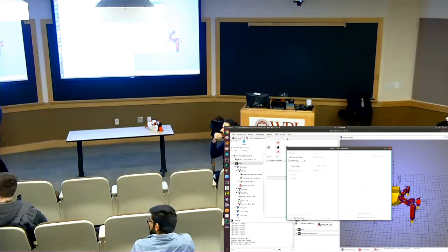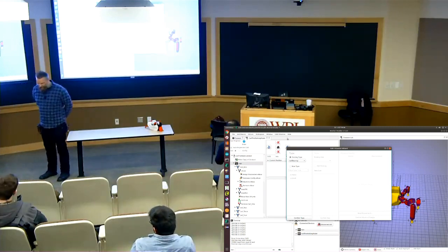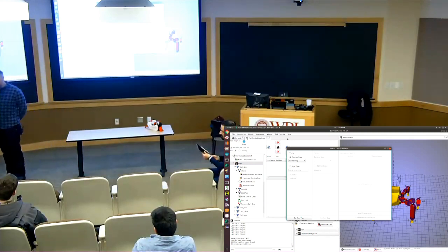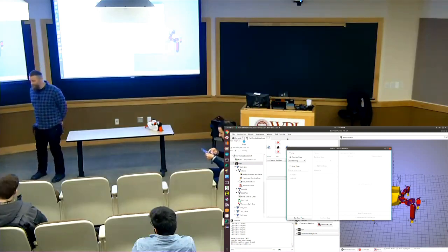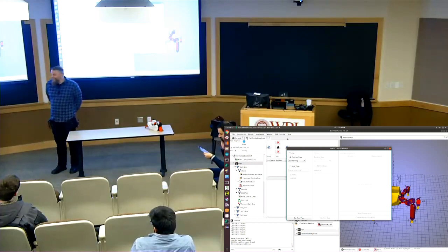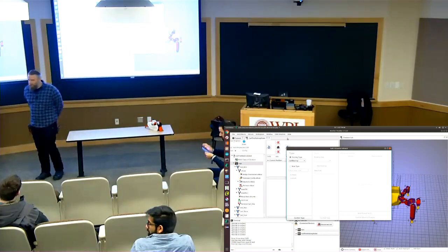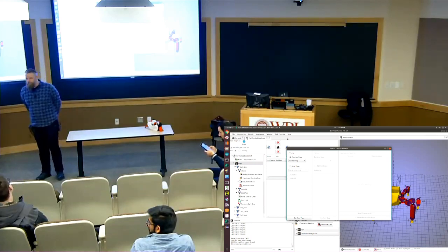How well does it handle fluid, soft stuff, elastic stuff? Not yet. I am working on an integration with a finite element analysis, which will do a little bit of mesh deformation analysis, but at the moment, the stiffnesses are assumed pure stiffness because again, we're dealing with smaller scale 3D printed parts, so for the most part, that's not even a bad assumption for us to make, given the force scales that I mostly deal with in this package. And again, if you go bigger, there are dedicated packages specifically for that kind of stuff, but not quite yet.